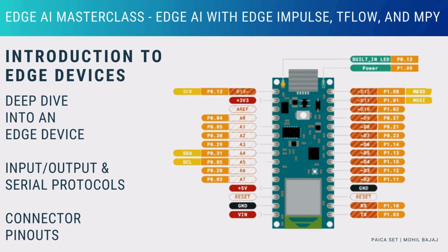Why not connect the external device directly to an analog pin? The reason is that many digital systems, like microcontrollers, cannot directly output analog signals. They would need a digital-to-analog converter, or DAC, which would increase cost and the size of an edge device, both of which are highly undesirable. PWM, on the other hand, offers a flexible way to simulate an analog output using digital means. This makes PWM particularly useful in situations where you need to control the power for devices that cannot easily be controlled by analog signals, such as LEDs and motors.